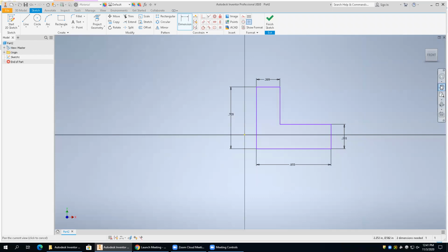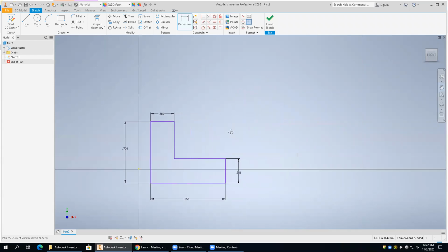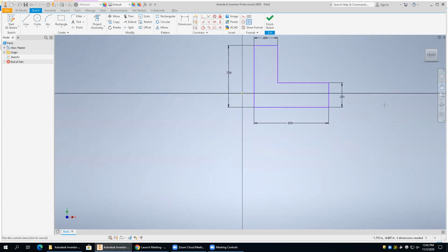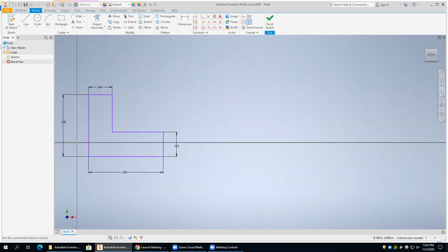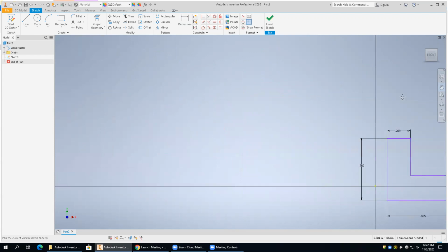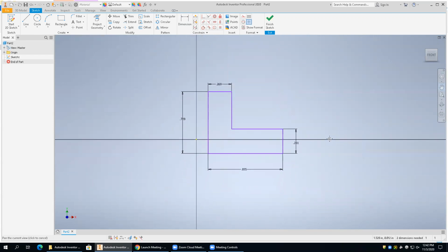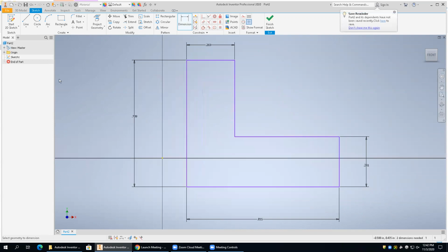So we also have the pan tool right there. That just locks you into a permanent pan so you don't have to hold the mouse wheel down. So all I'm doing is once I'm in that pan mode, I can just left click, drag, left click, drag, left click, drag kind of thing. Okay, everybody getting that to work? When you're done, you can just hit the escape key and you're back. Okay, so let's go ahead. We're going to do a zoom extents or a zoom all, bring it back to that normal view right there. We're going to have a little bit more to say about some of these zoom guys here in a minute.